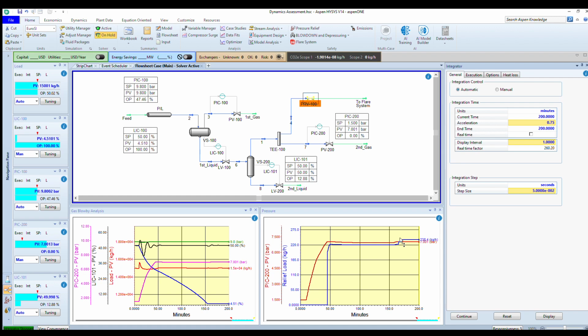But when it comes to existing facilities, to reinstate the code over-conservatism retrospectively is so demanding from a time perspective and cost perspective. So you need to migrate a little bit from the steady state concept to the dynamic concept to see the accurate prediction, specifically for relief systems.